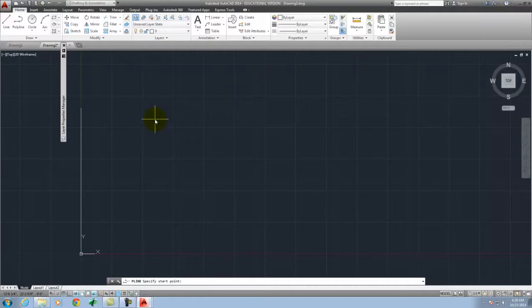Now go to the View and hit Extents. Now you can zoom out just a little bit. It's actually not Control plus and Control minus anymore, it's just the scroll wheel anymore. Use the little scroll wheel, there you go. I'm going to walk around, make sure people have gotten here.